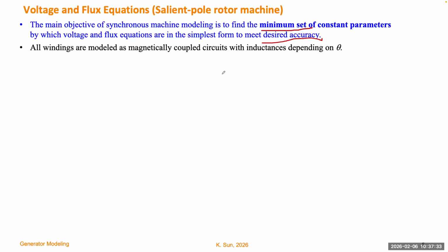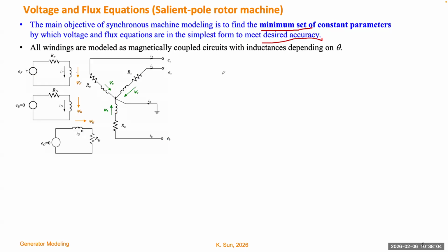For a 2 winding transformer, each winding will have a circuit. The 2 windings don't have a physical connection, but they couple through the electromagnetic field. So you need to introduce a parameter, the mutual inductance, to model how the current on one winding can affect the other one. So we borrow the same idea. Now we have 3 stator windings and 3 rotor windings. That may remind you of a 3 winding transformer, or a 3-phase transformer. So let's draw the circuit.